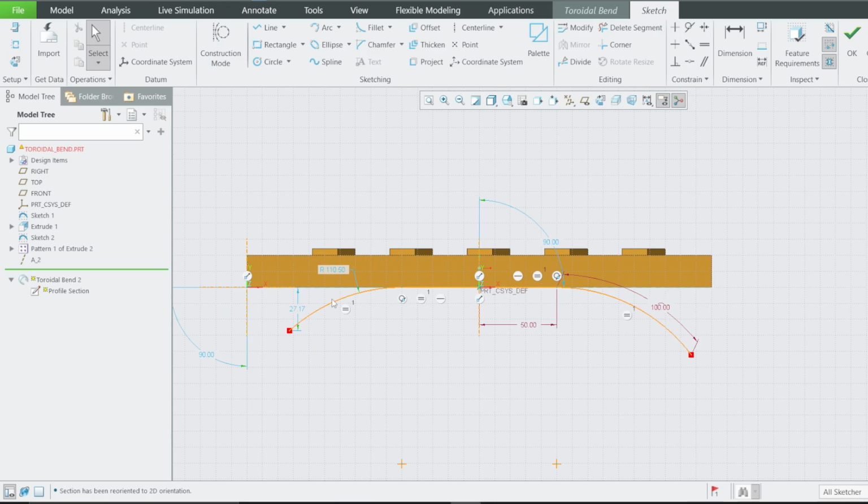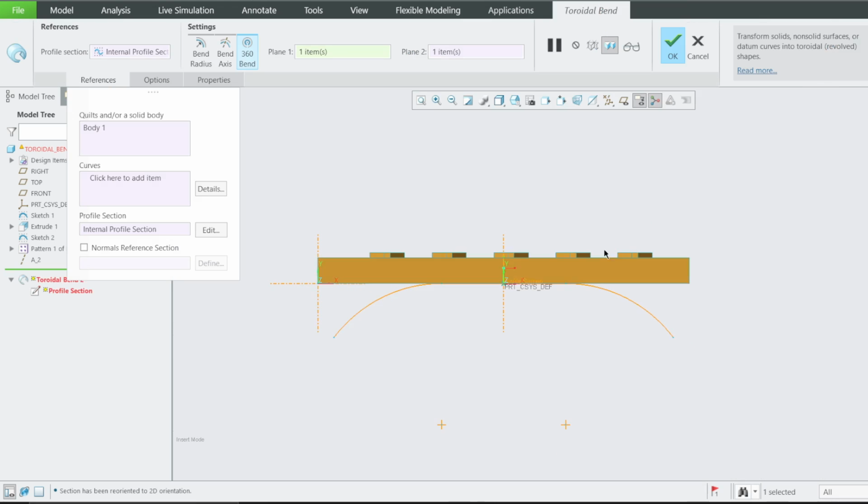It has to be 100 for this to work. The length of your sketch should be exactly the same length of this face. Therefore, I need to define something else here. From this point to this point to this point to be 100 also, for this to work.